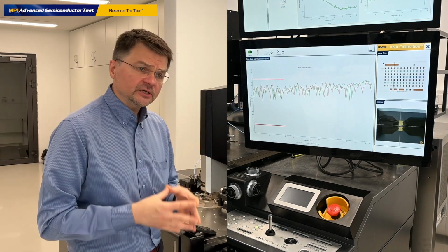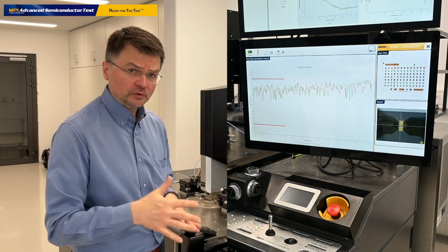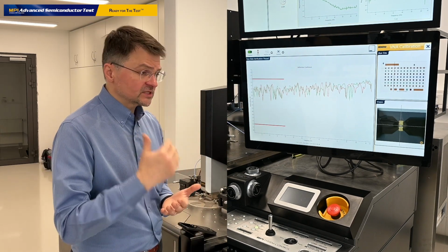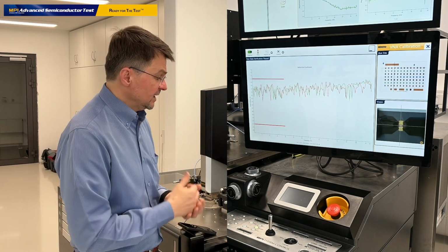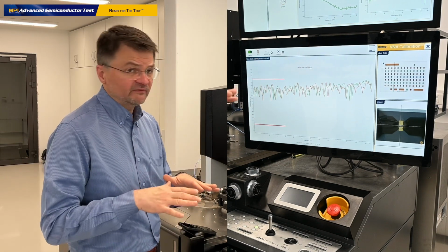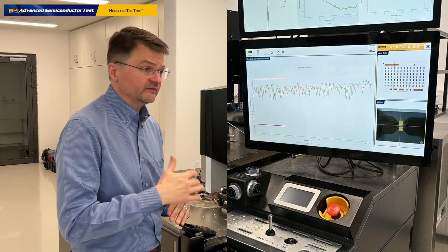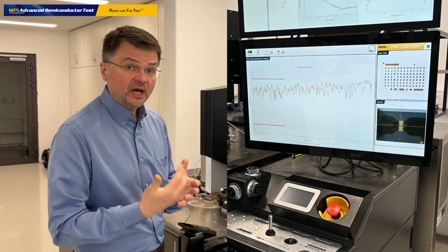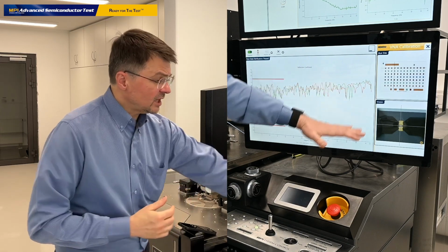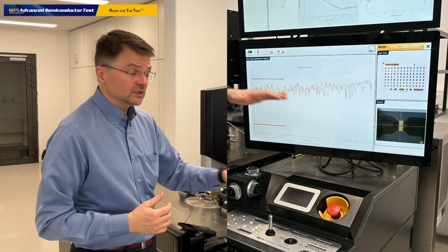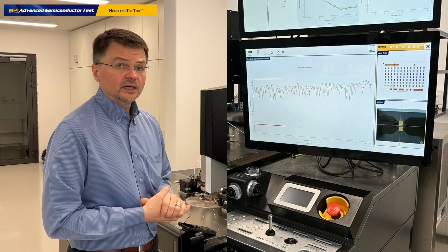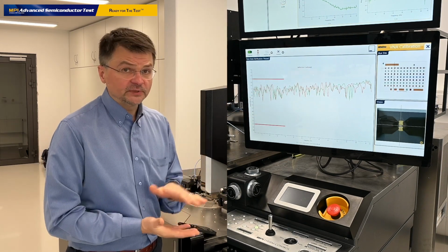There are several criteria that can be set up for the raw data to understand if your contact was good and if your standard is of a good quality, such as the maximum value of the return loss or the maximum value of the insertion loss of the transmission standards and some other specific criteria. What we currently observe on the screen is the return loss of the through, measured S11 and S22, and predefined boundaries for acceptable data results.